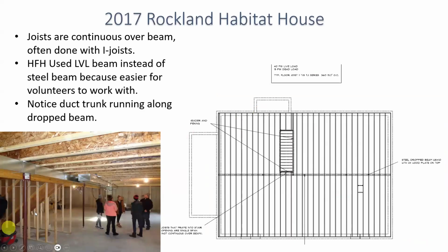So this is the stair. Here's our LVL beams. Here's our FHA columns. So FHA stands for Federal Housing Administration. They're rated columns for a certain load. They'll have a label right on them that'll tell you how many thousand pounds they will take. They're adjustable. They've got a little screw-in piece at the underside, and these are installed the right way, where the screw-in is supposed to go down. It's not supposed to go up. And in some cases, it goes down and you don't even see the screws after the slab's poured because the slab covers up where the screws are.